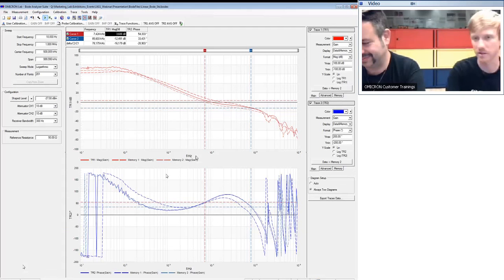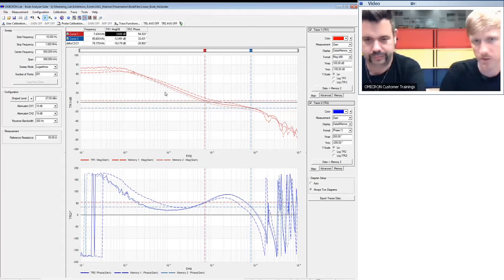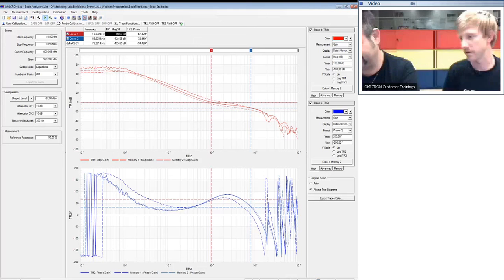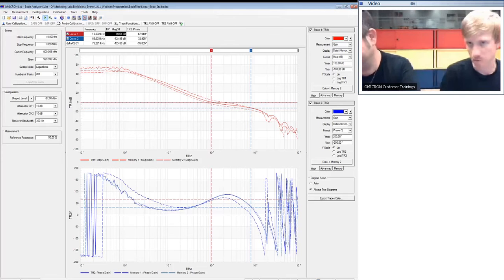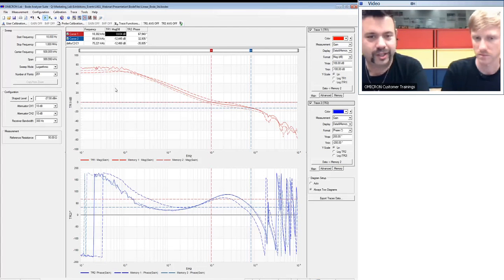And we can see that, again, the system behavior has changed. So we have now a third curve with different system behavior. The crossover frequency has changed a little bit, and therefore also the phase margin. But this time it got better again. So we now have nearly 70 degrees of phase margin with that input voltage. So the higher input voltage did improve our phase margin in this case. Okay. So this is how you do the measurement.